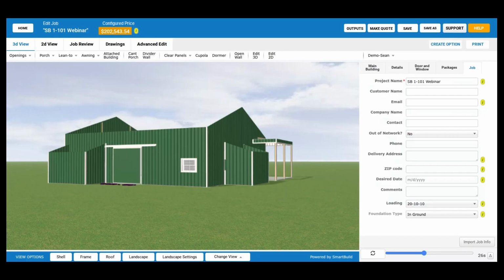So does that make sense? Yeah, but where I'm confused is, I'm configuring for somebody in an area right now that has a lot of different wind loads. So we have four criteria, and that is wind load, building height, bay spacing, and then building width. In that order, those are the four most important things you look at. And then from there, you would choose whatever column you're going to use. So I don't see bay spacing in there, because out west here where I'm configuring right now, there's a lot of different bay spacing options.